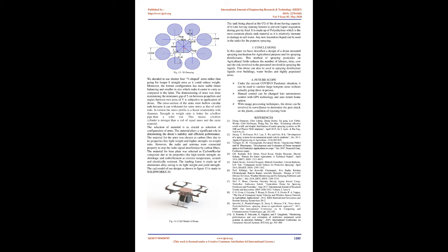2.8 Structural description. There is no such generic frame which is considered to be best among all the frames, however it depends on a number of factors like multi-rotor configuration, rotating moment and balancing, application, material, stiffness and components integration. Depending on size and dimensions of selected electronic components, we designed a base plate in the shape of irregular octagon such that all components are placed on the center of gravity. The dimensions in mm are briefly mentioned on figure 13.